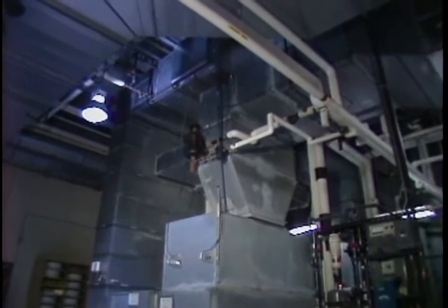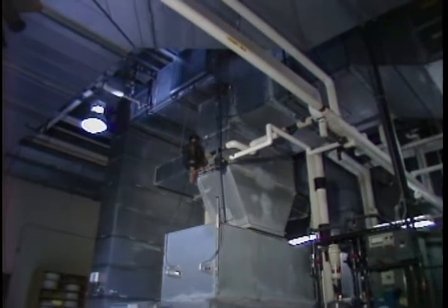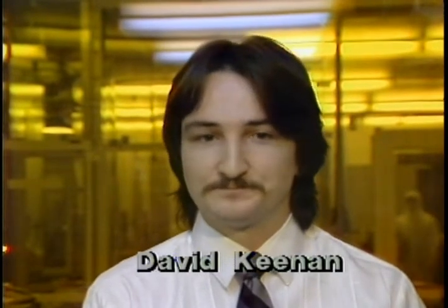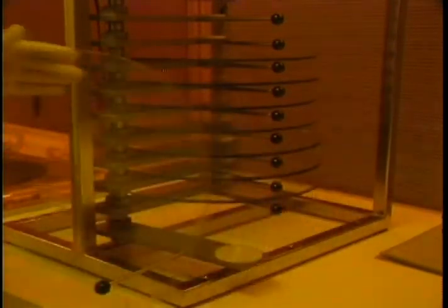Well, the human body gives off something like 2 to 200 million particles a minute. It's just a little volcano. Every action that you do generates more particles. To operate in a Class 100 environment, usually the hardest thing to deal with is the air that's blown around and the people that move in it. We control the quality of the air by using high-efficiency particle filters, HEPA filters. In the clean rooms, all work is done under yellow light to avoid accidental exposure of photosensitive coatings.